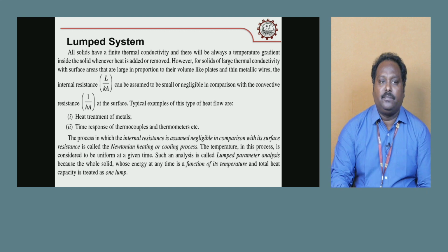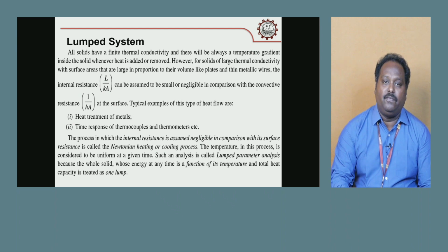And let us see how the lumped system works. All solids have finite thermal conductivity, and there will always be a temperature gradient inside the solid whenever heat is added or removed. However, some solids have large thermal conductivity with surface areas that are large in proportion to their volume, like plates and thin metallic wires.